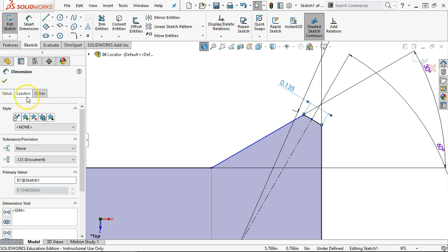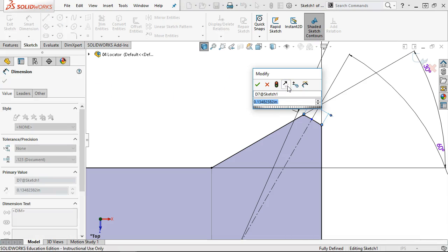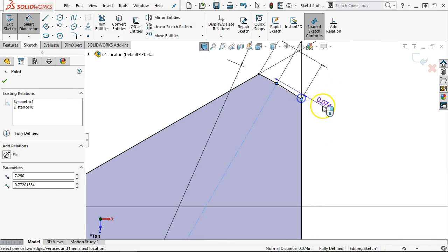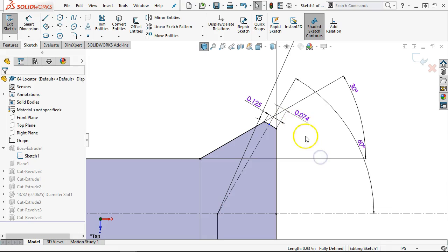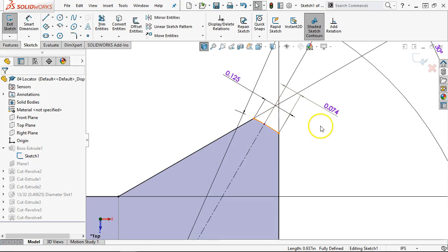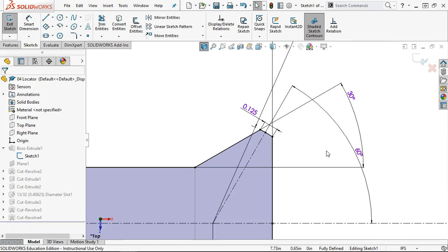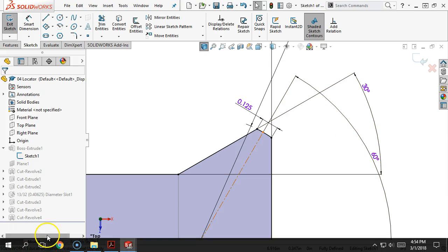All right, so if we're really going to try and drive this into those dimensions, I'm going to take that dimension off of being driven and make it driving, 125. And then dimension says that one side will be 062. And it went over defined, and I accepted it, and so it's not really picking up that dimension. So other than that being coincident, it goes back to being fully defined, but I can't really bring it to that 062 when the 074 is what comes off of the 60 degrees.